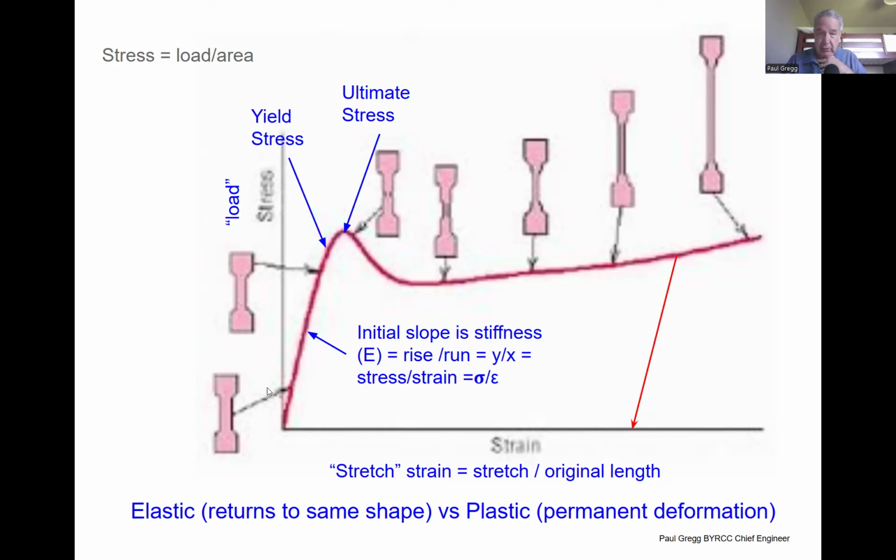So typically you do a tension test. It starts to neck down here. It starts to get thinner, and then it gets really thin and long, and that's where there's a lot of strain. Okay, and spaghetti only goes up here and breaks. It doesn't have this stretching capability, but the glue does have a stretching capability.